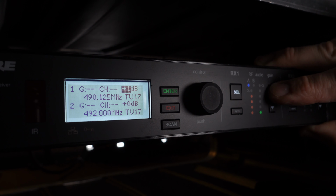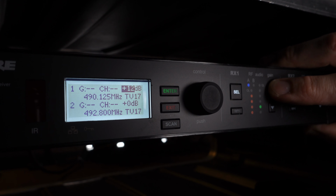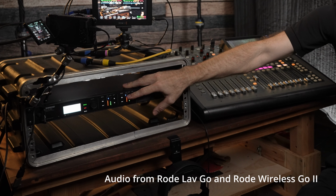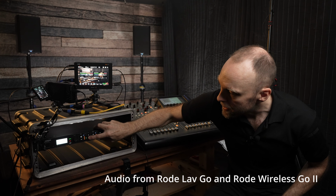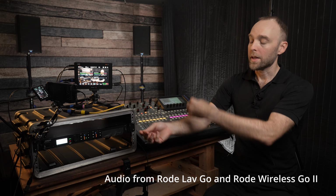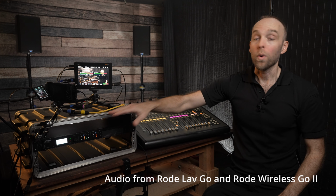So I'm just going to keep gaining this up, check, check, 1, 2, until I hit a level where if I do get loud, it won't clip out here either. Let's leave it there. Let's leave it at plus 13. Why plus 13? Because that's the level that I need to gain the signal up to electrically for this receiver to have what it needs.